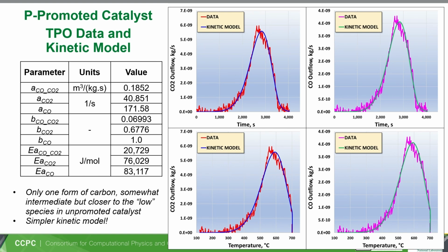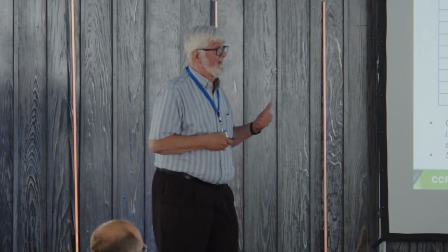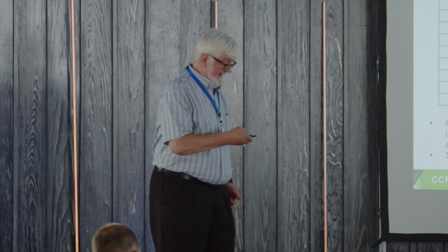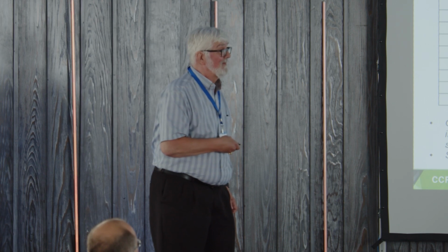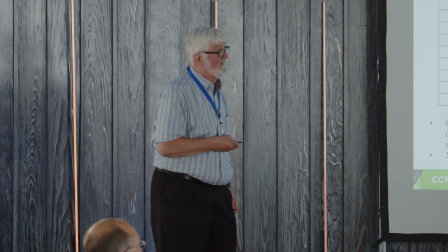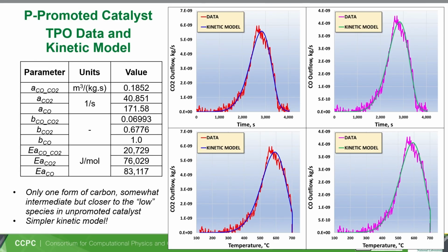CO-CO2 ratio changed too. We need to plug all these things into the Barracuda model, but still, it's interesting. Maybe the phosphorus is making coke combustion more facile, right? And it also helps me eliminate 5 reactions or 4 reactions, which definitely helps it compute faster, right? And this is ongoing right now. I wish I had results to share with you guys, but we're just not there yet.